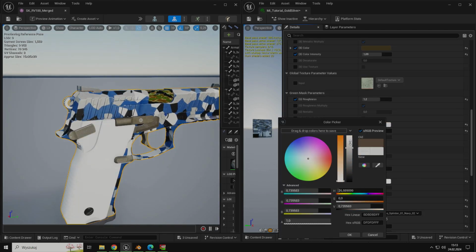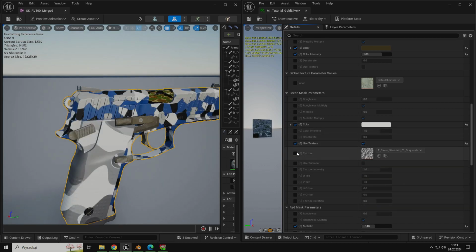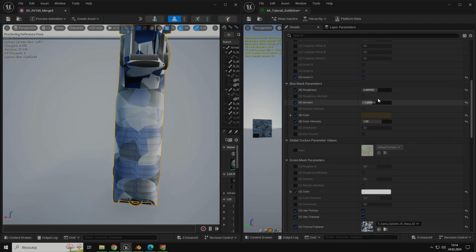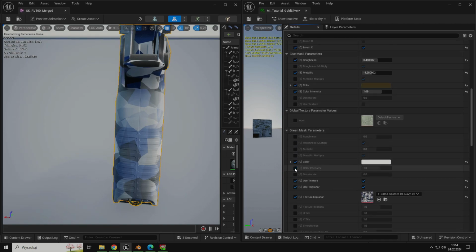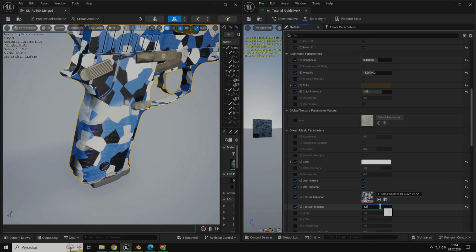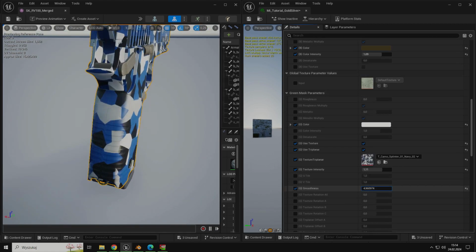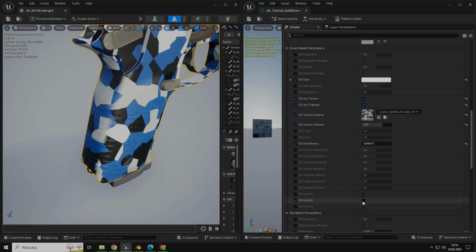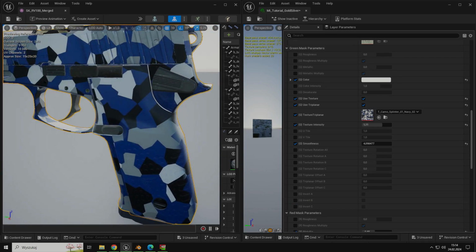When working with the texture on the grip, we can choose between a blurred transition in the center or a sharp one. Neither is great, so I decided not to use triplanar in this case. Most of the grip texture is in one piece on the UV map, so we can have a continuous look without using triplanar. In this case it looks even better.